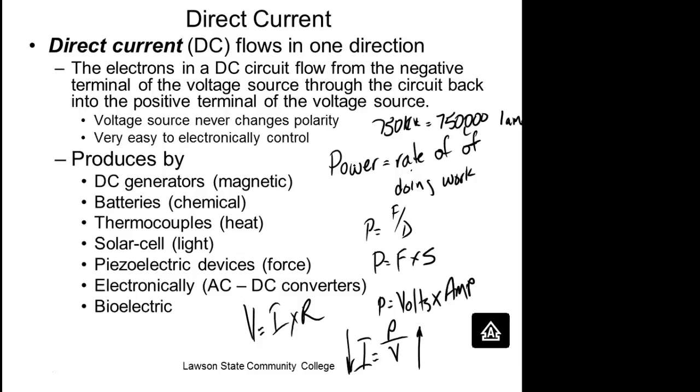Because when they tried to send that current out, the conductors were dropping all the voltage because they can't change the voltage, right? You understand? Now, what advantage does high voltage have over low voltage? Well, the higher the voltage, the less current required to do the work. That makes sense. Okay. But what's the problem with the higher voltage? It gets more dangerous, right? So they couldn't use 1,000 volts DC to lower the current, because people would be getting killed all over, right?